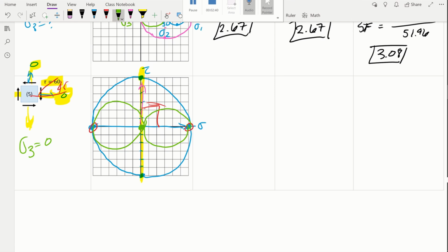Still, we want to draw these, right? We have the Mohr circles. We want to look at the biggest one, and we want to ask what is the highest value of sigma. Well, it's going to be either this point or the other one. They have the same magnitude, so the sigma max is 60 in this case. What is the maximum value of tau? Well, it'll be this guy here, the absolute max, which is also 60.